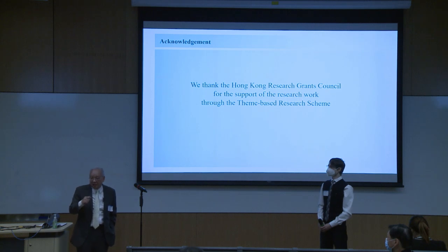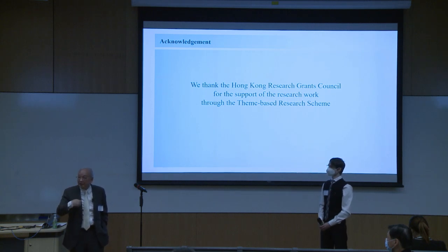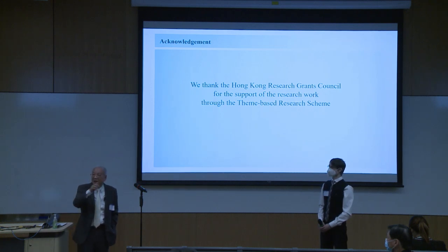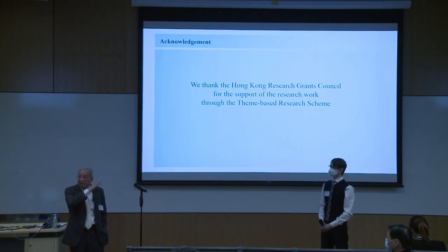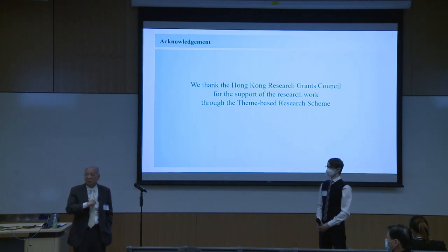It turns out they invited us to their exhibition to share with their customers what kind of things we can do. But we limited the operating frequency to 300 gigahertz. Beyond that, the resolution of that 3D printer is not good enough. But for any lenses working below 300 gigahertz, it will work perfectly.